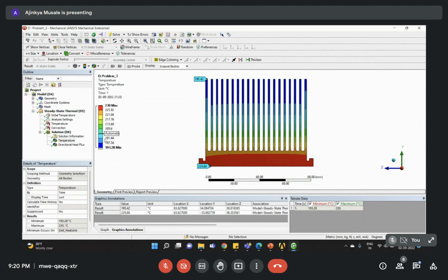Correct. So yes, while designing such heat sinks, you can take help of these calculation results. You can decide what amount of thickness is necessary and how many fins are required. Those trials you can perform over here, and you can decide what the optimized design is for you, or which design gives good results in terms of number of fins, thickness of fins, or even height or width.